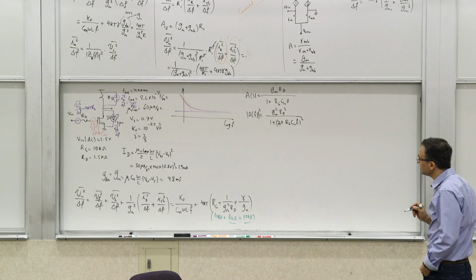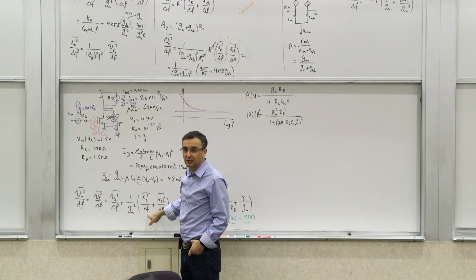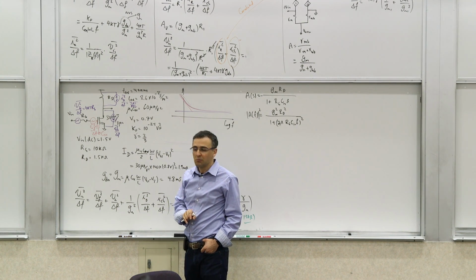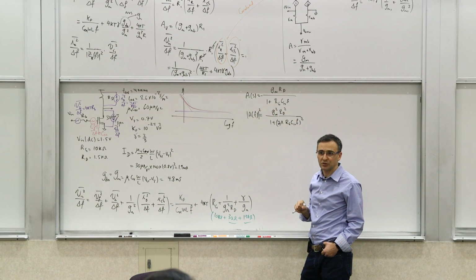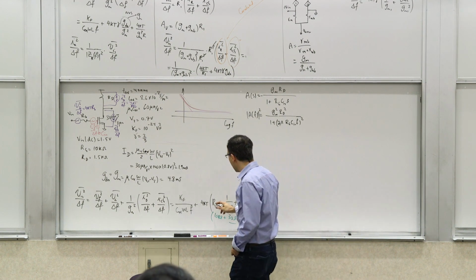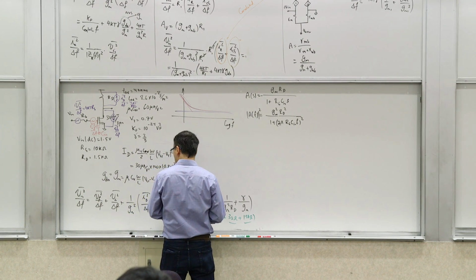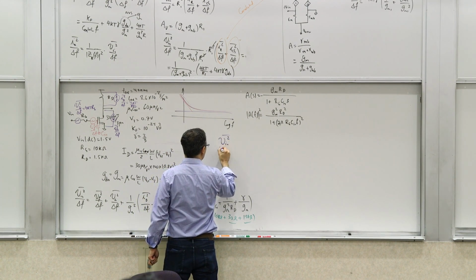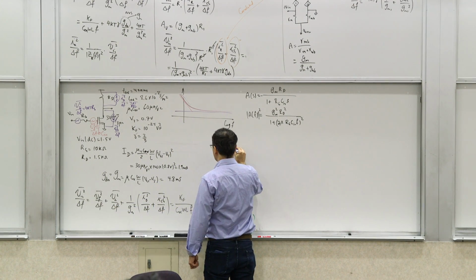So now these output noise sources that you had, they get multiplied by RD to produce the output. They get divided by this transfer function. Before, you had divided only by the top part of the transfer function, GM RD, and the RDs cancel, and you were left with GMs. So what would change here is that now instead of this, you will get a different expression. So now these two terms will change. So now the new Vin squared over delta F would have the two input parts of the noise. Let's keep them in those forms for now.